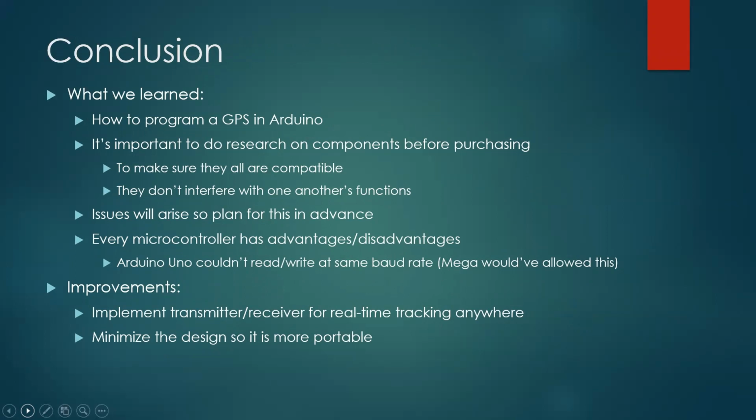Definitely realize that issues will arise no matter what, so plan for this in advance. And every microcontroller has advantages and disadvantages, and it's important to recognize those beforehand. Like we realized a little late in the game that the Arduino Uno couldn't read and write at the same baud rate, but we did a little more research and realized that an Arduino Mega would have allowed this.